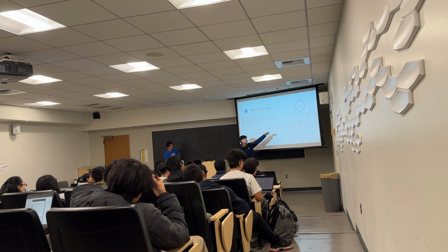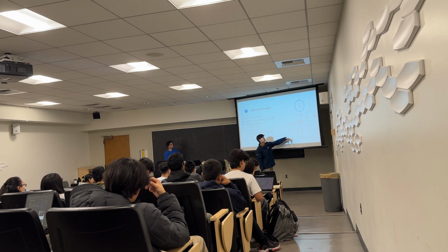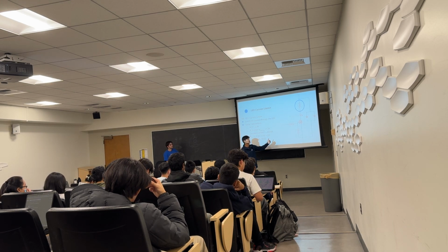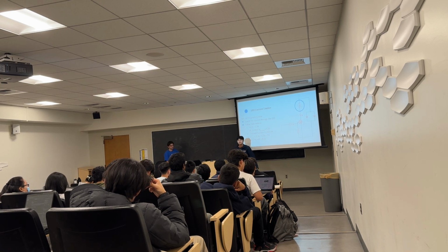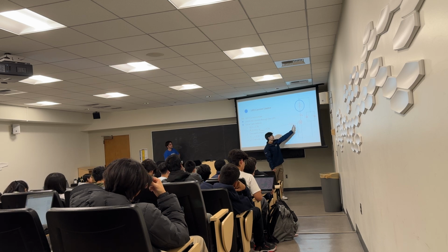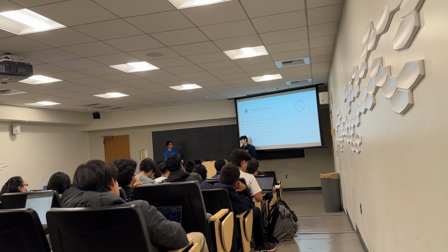So it's just going to go through the 2 capacitors and then to ground, right? But as soon as we turn on this MCU, it's going to allow current to flow in this branch, in which case it'll turn on the IR emitter, flow down to the transistor, and then back to ground. And then right when you turn it off, this path is going to be closed again, and then leftover charge is going to go from this to ground through that resistor. Got it.